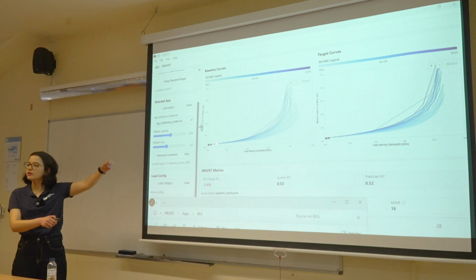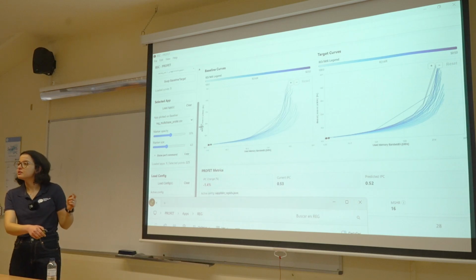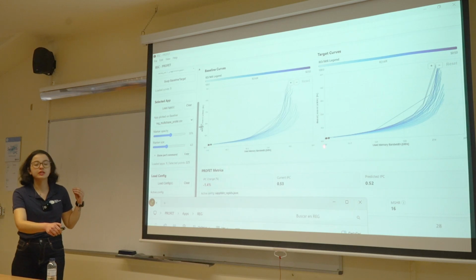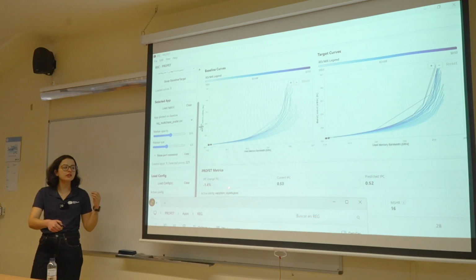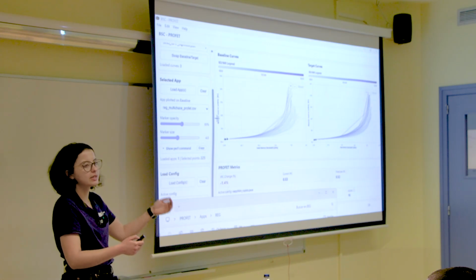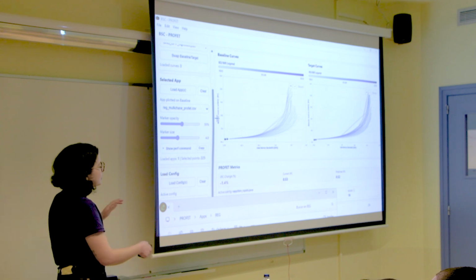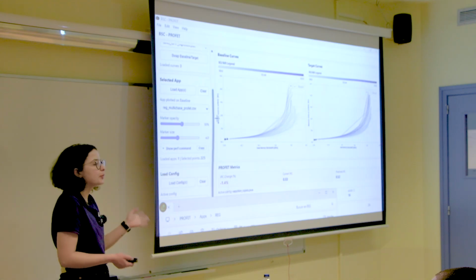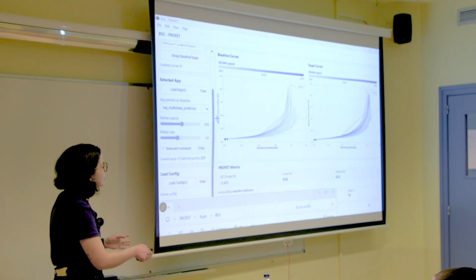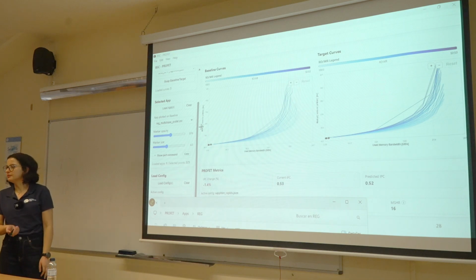So this was profiled, it was measured on hardware, and the dots we are seeing here are predicted. So I predict the position of the dots here. And also you see the IPC change. IPC here is performance. So instructions per cycle, we are talking about performance. And we see a decrease of minus 1.4%. So we are talking about 1%, which is almost nothing, because the lead-off latency of the curves is very similar.